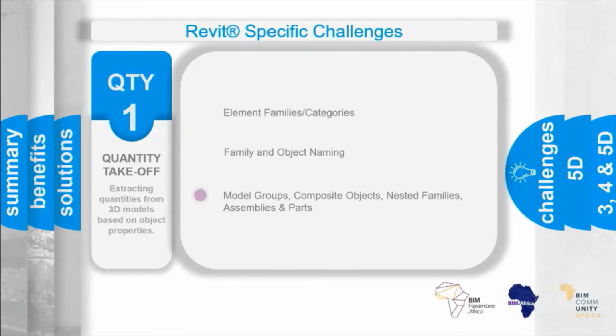And this is as the object data sits behind the protection of the group. So as a result, in order to access that, in order to classify it and pull the quantities out of those objects, we've needed to ungroup those model groups. And this is done by selecting the entire model, filtering for groups, and clicking ungroup multiple times until we've removed them. But the problem with that is if we're doing that in a live model, we are editing the model author's efficiency. And if they need to come and make a change at a later date, we've now removed the tool that allows them to make that change efficiently. So we need to be very careful about who's going to do that.